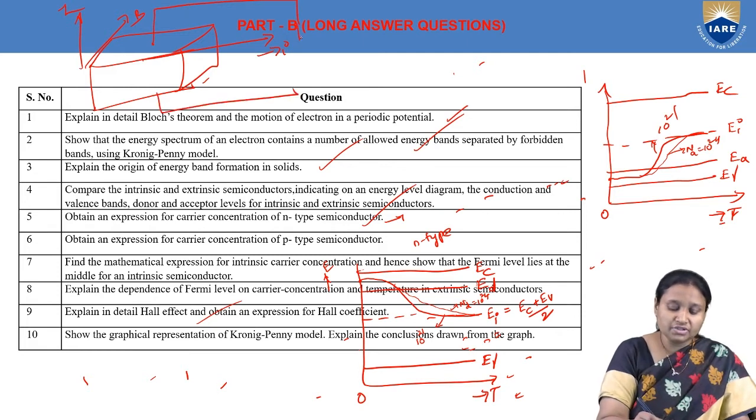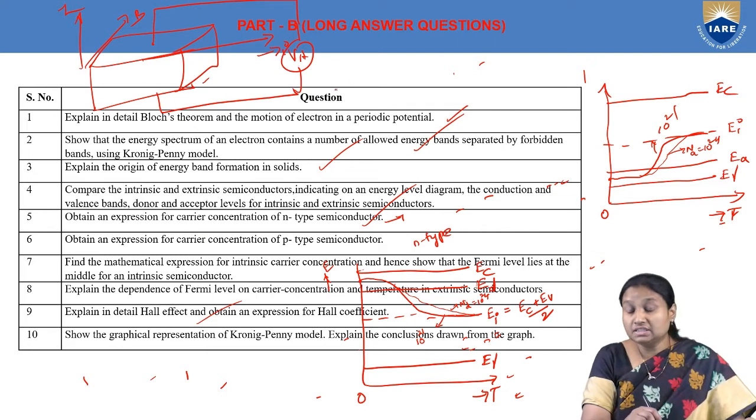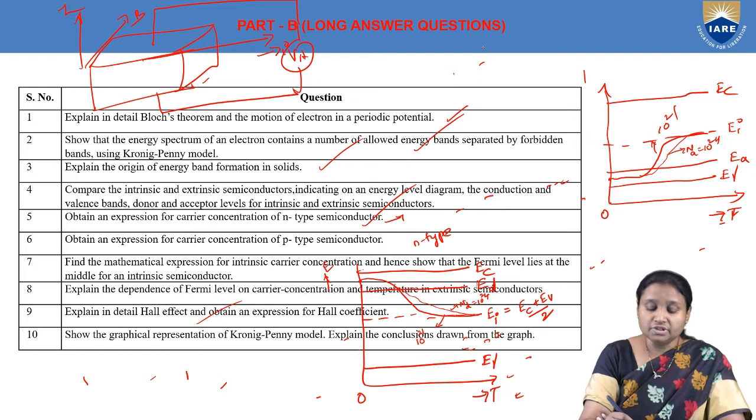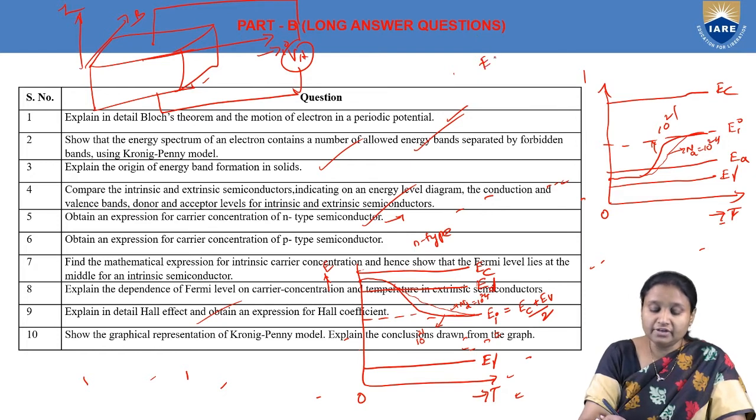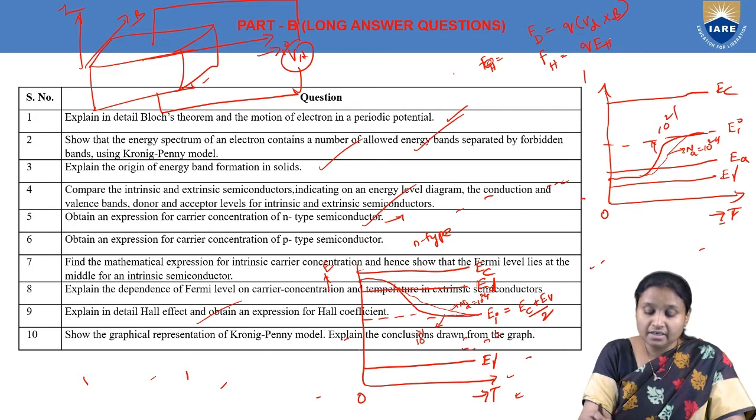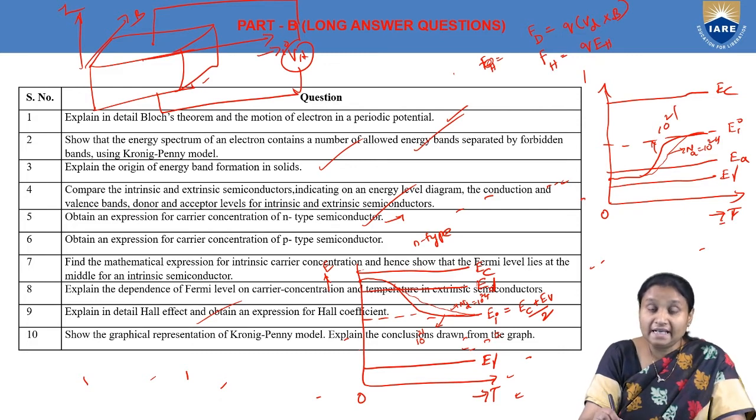So we have generation of Hall voltage, and here charge carriers inside this material are subjected to two forces. So first, due to magnetic field, it's a deflecting force, it is given as Q into Vd cross B, and then Hall electric force, it is given as QEH. And what we'll observe here is at equilibrium both these forces will get balanced.